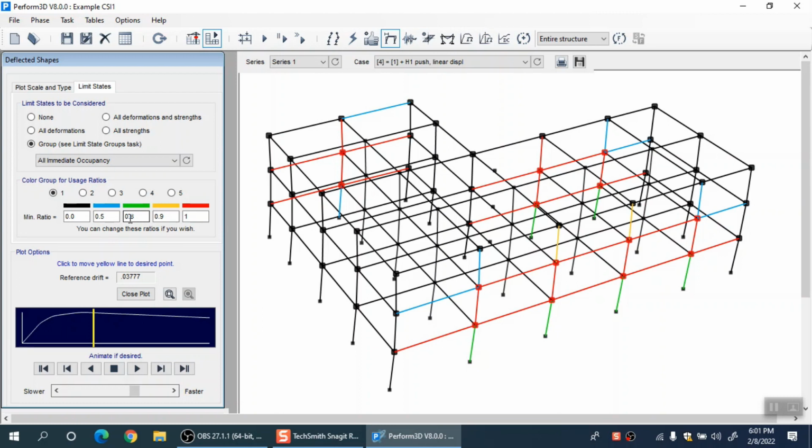So, we can qualitatively make for example our own range. For example, we could call them damage classification as low, moderate, severe, complete, right. So, severe means 0.9 for example, or 0.8 to 0.9. Complete means gone already, red color, right. So, this gives us a qualitative idea also about where the actual strain or actual deformation lies relative to our given capacities, right. As I have said earlier, the program will directly report analysis results. Any decision making which is related to structural design or change in design, you are the one who will perform that actually.